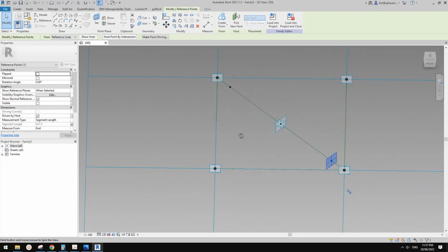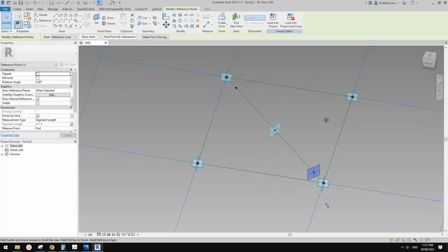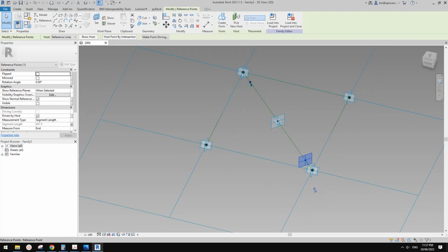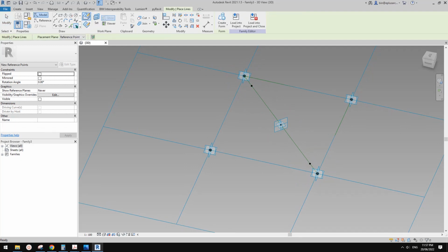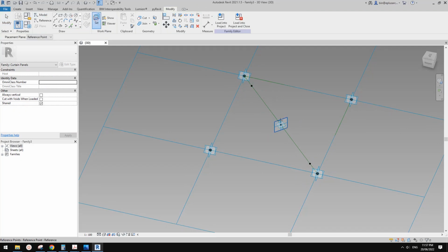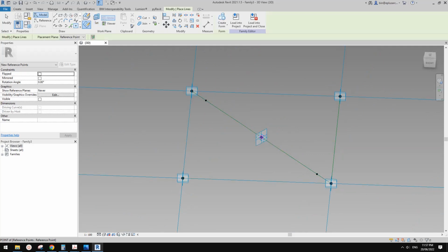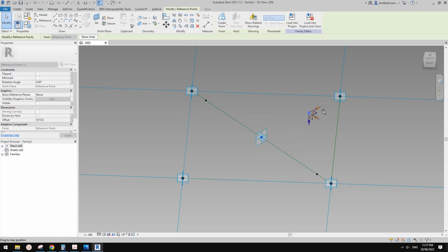And then we need to find another 2 points, because we need to rotate, we can't just create a reference line and use the same method. So we need to use point and draw on work plane, set work plane. This time pick the vertical, so this one, and place it on this point. Select this point, drag it to this direction. Just roughly place it here.